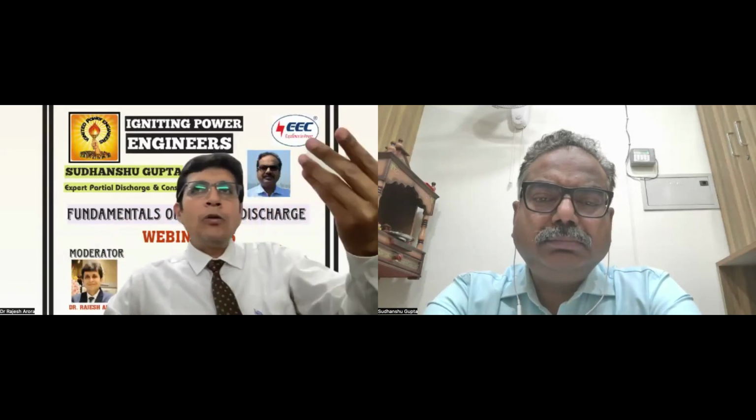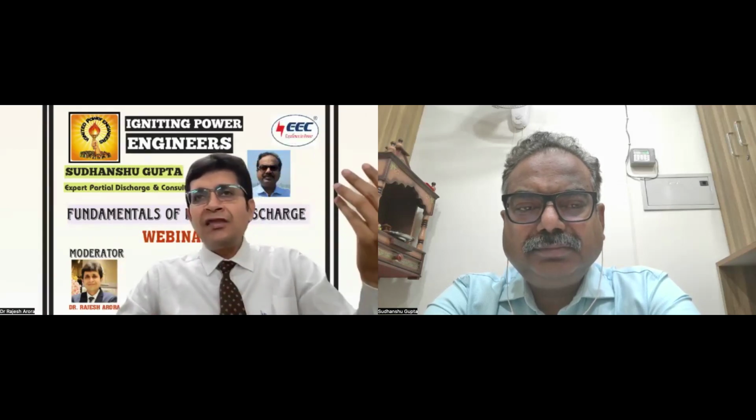When we talk about partial discharge, the most confusing thing is the unit used across the world for partial discharge measurement. Most of the time, when you go for inspection, you measure everything in picocoulomb, pC. That was already described very well by respected Gupta Sahab. It varies from equipment to equipment. For my GIS, we usually talk about 5 picocoulomb.